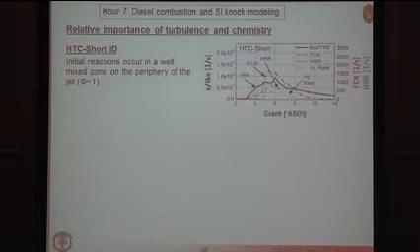And you can see that it increases. Why does it increase? Well, because the injected jet creates turbulence. You have gradients in the mean flow that are generated from the injection, which create a production term in the k and epsilon equations that lead to the production of turbulence. So you can see this black curve rising here, even before we have significant fuel consumption. FCR is the fuel consumption rate.